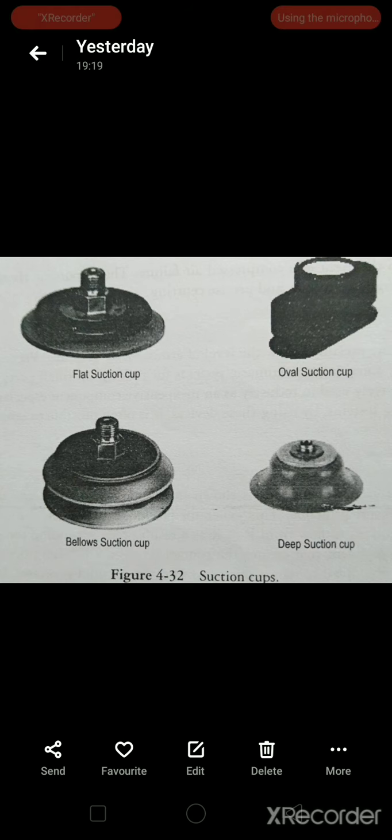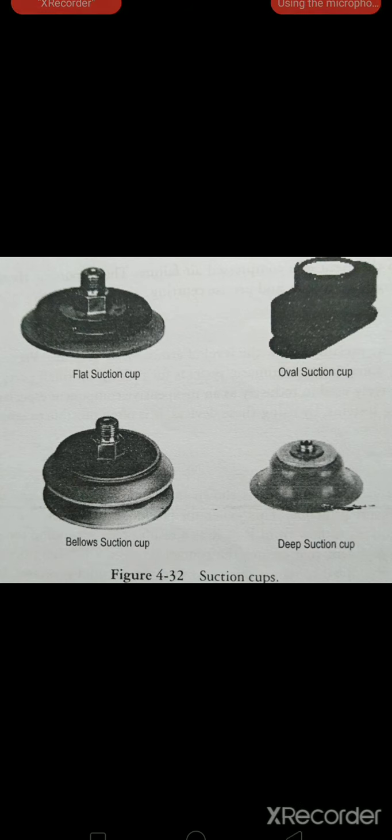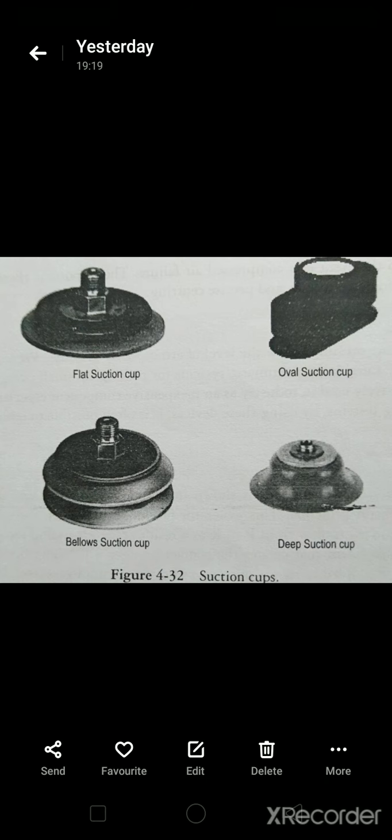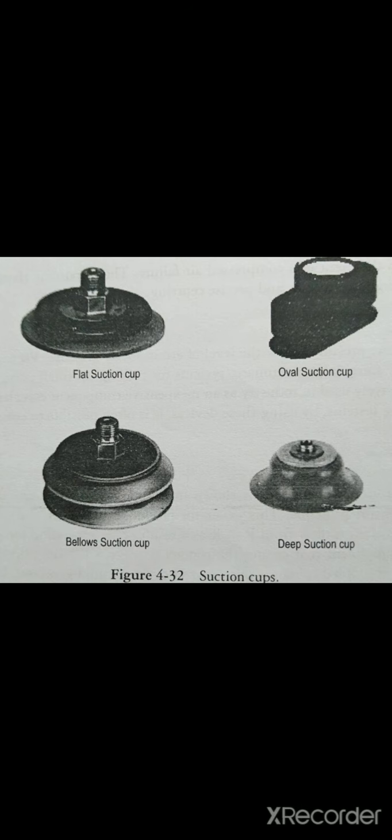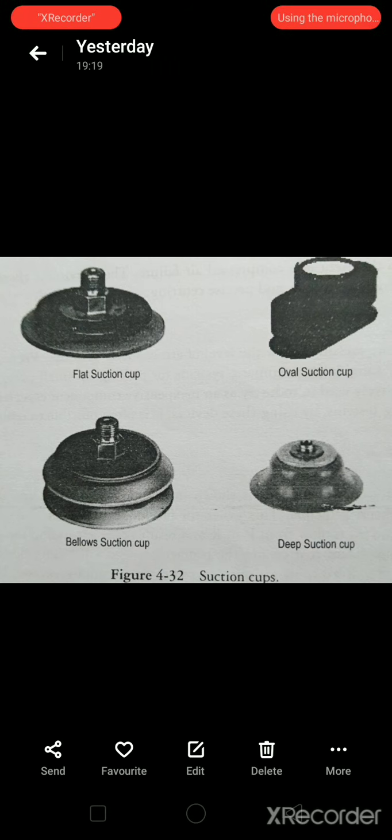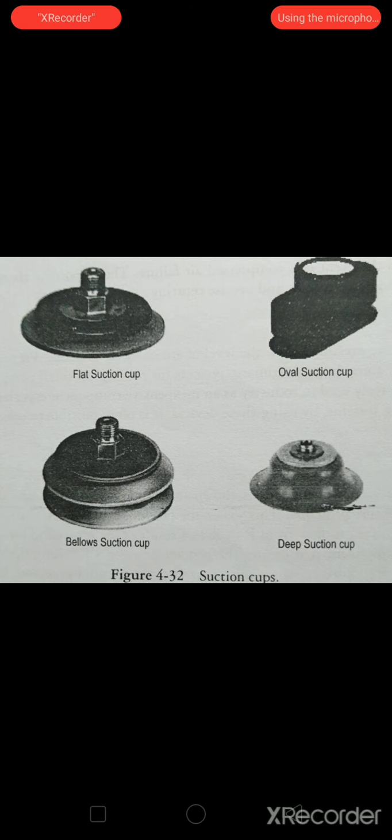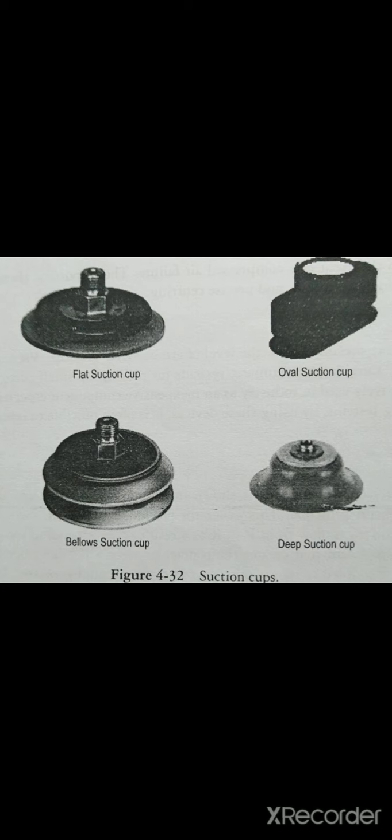Applications of vacuum equipment: they are extensively used for lifting and handling many types of products and materials, permitting many ways of holding, picking up, transporting and setting down workpieces. For handling operations, compact vacuum generators with a wide variety of suction cups made of different materials and vacuum switches can be used. The industrial robot is an important handling machine that roughly imitates the human arm with the application of a mechanical hand in the form of grippers.